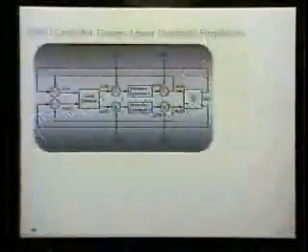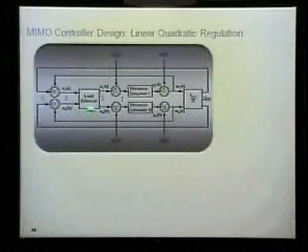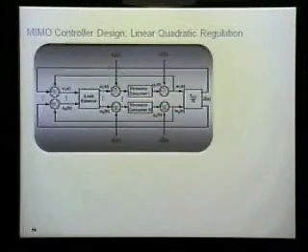Okay, since this is a multiple input, multiple output system, there's some additional dimensions to how you do control that are sort of interesting. And especially for this kind of system, because we've got this sort of inherent trade-off here between minimizing the response times by being accurate in the regulation. By accurate, I mean we've driven all of the incremental response times for the pools to the same value. That would be accurate. That's corresponding to the accuracy problems we saw before.